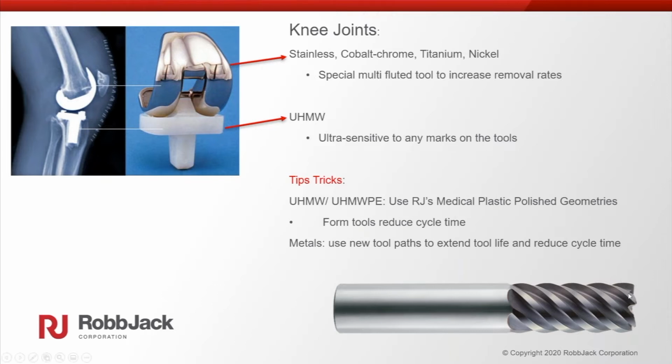You'll look at this tool underneath a microscope. This wouldn't be a tool for the plastic. This would be a tool for the metals. But if you looked at the tool for the plastics underneath the microscope and you're looking at this cutting edge, even underneath a microscope, it looks flawless, but you'll get micro scratches and mismatching and things like that on these UHMW or medical plastic parts,